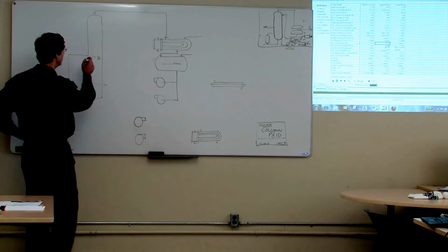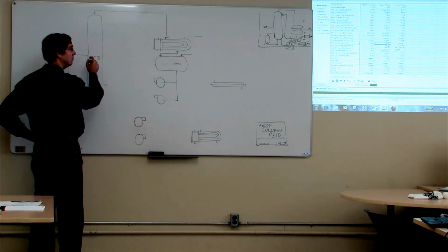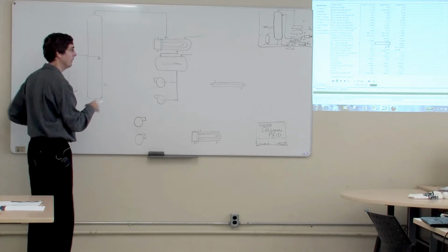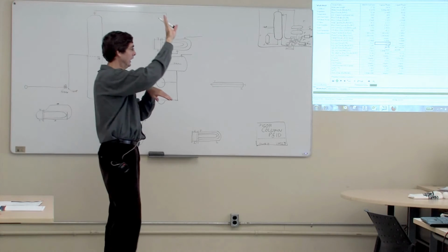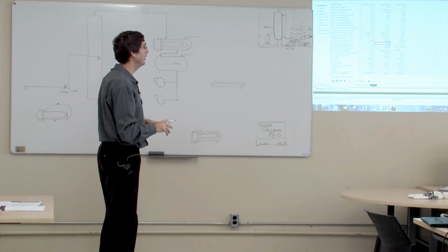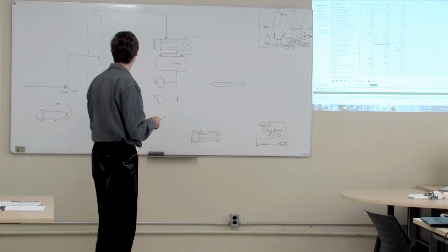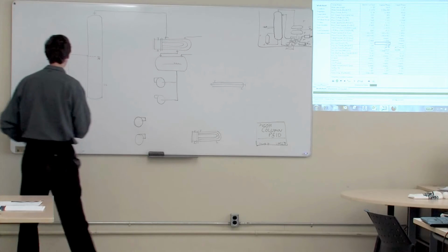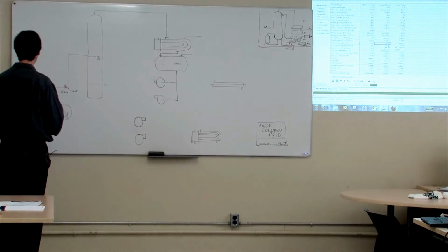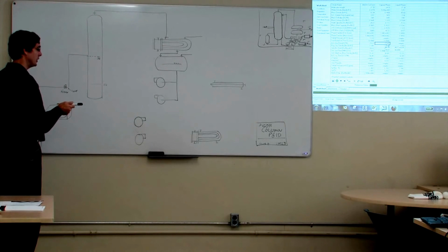So I'll bring it in either on a tray or at the top of a downcomer, so that when it comes in, the vapor can go up and the liquid can go into the tower itself. That's what I think I can do, but maybe you guys can just confirm that. And that's coming from sheet 1.